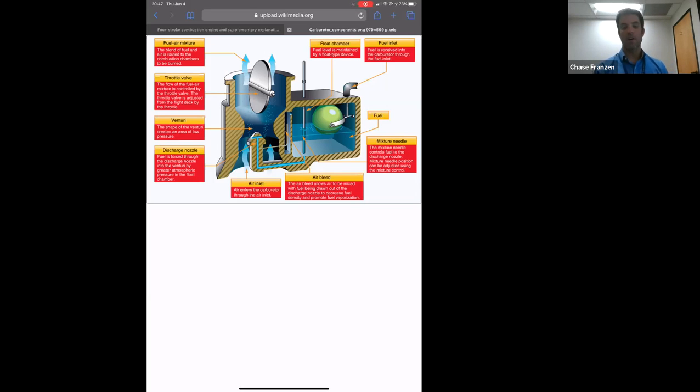Primer. So as you run through your Cessna 172 November checklist, it asks you to prime. It's on the left-hand side. As we open the primer, as we draw it back, it's like a straw almost. It creates suction, and that actual plunger fills with gas. And then as we push it, it injects the gas directly into the number 3 cylinder of the Lycoming O-320 engine. So as we prime, we're just dumping some gas into that cylinder so that when we engage the starter and it turns the crankshaft, the engine catches.